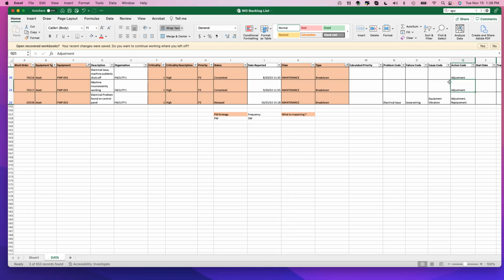But the third time, now that we're seeing that it's not behaving correctly all the time, then probably a replacement around that wiring or around that vibration control might be our solution to either permanently correct the issue or at least maintain it before it's happening again.